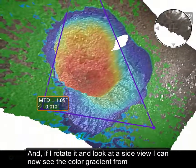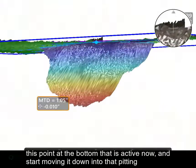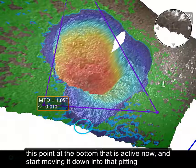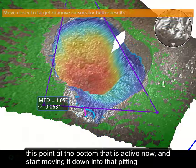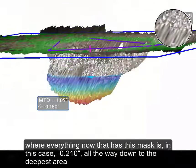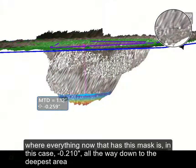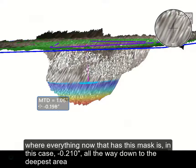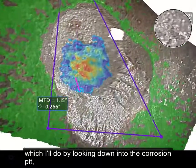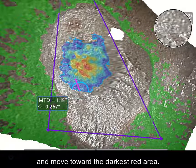And if I rotate it and look at a side view, I can now see the color gradient from this point at the bottom that is active now and start moving it down into that pitting. You'll see, you can look at it from a cross section where everything now that has this mask is, in this case, 210 thousandths, all the way down to the deepest area, which I'll do by looking down into the corrosion pit and move towards the darkest red area.